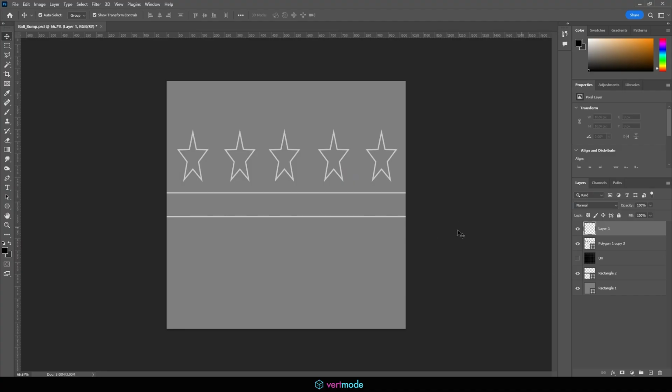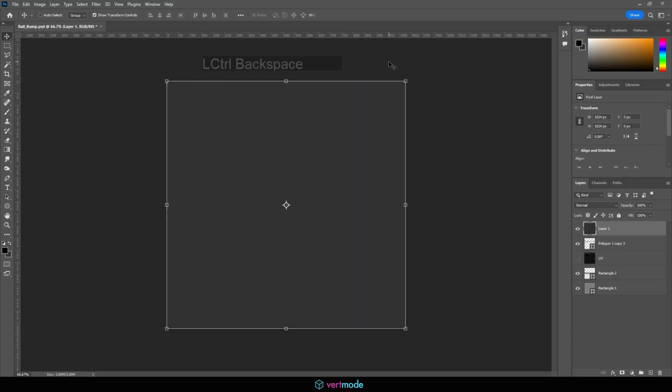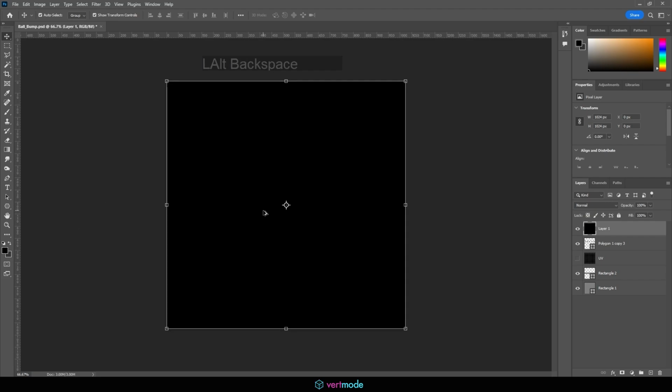And with this, I can fill in the layer one of two ways. You can either use Alt plus backspace. So that's what I did here. I held down Alt and hit backspace to do the front color, and that will fill in the layer. Or you could use Control backspace to do the other color. You can see my secondary color is that gray. That's what's filling in that layer. So I want to use Alt backspace as my hotkey to fill this in, and that's going to give me a solid fill layer of pure black.